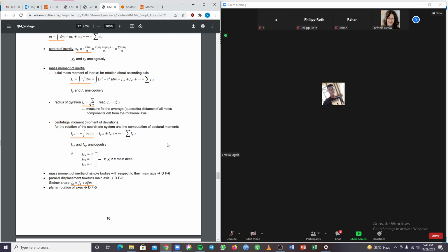Okay, hold on. It concerns two symmetrically arranged brake levers, and I was trying to apply moments and other things, which I got the steps right, but when I tried to check my answers, I was not getting it. I was off by 50 newtons. I was getting 300 newtons while they were getting 250. And for me to calculate my braking torque, which is the friction, I don't really know how I'm going to explain it.